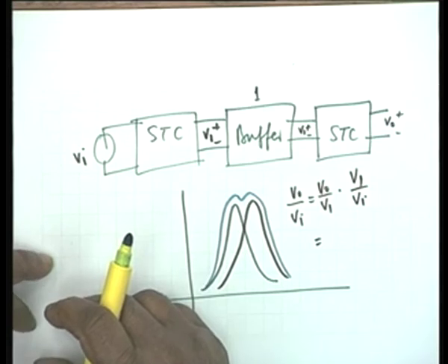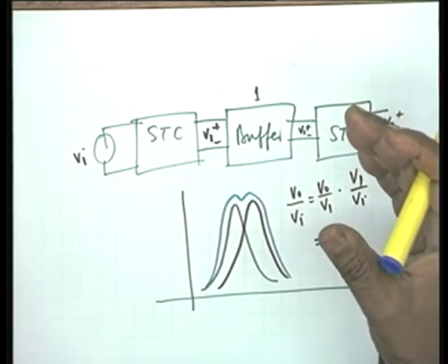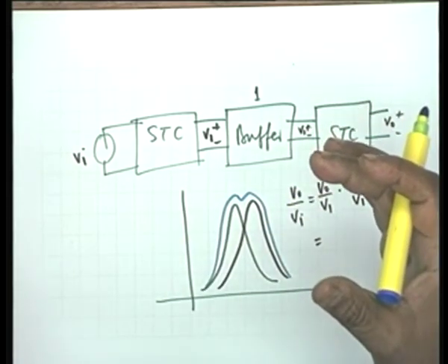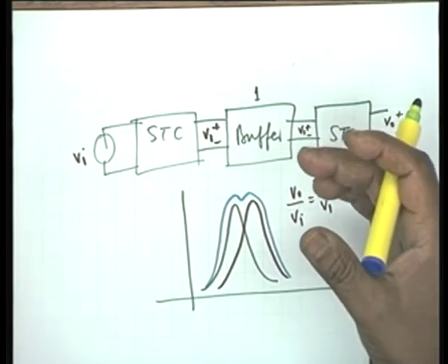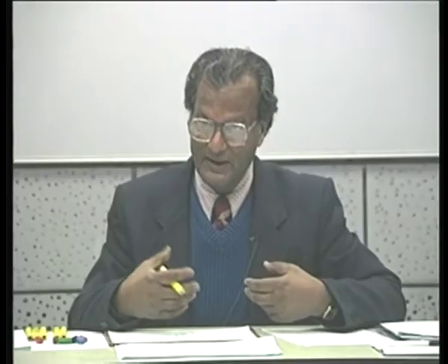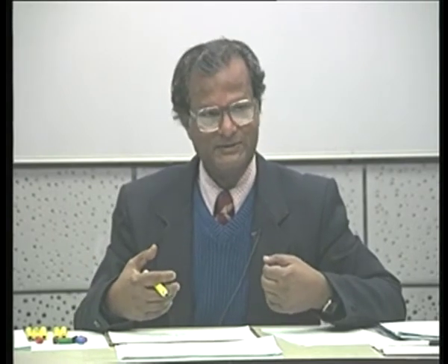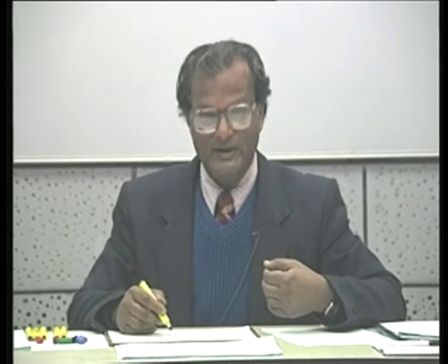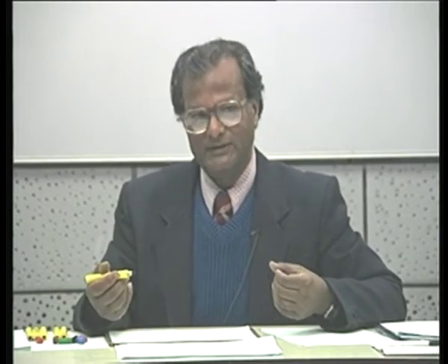Okay. So, you can combine two single tuned circuits without magnetic coupling, without resistive coupling, without capacitive coupling, to form a double tuned circuit response, to form a wide band selective response by simply doing this. You require an active stage, a buffer in between.